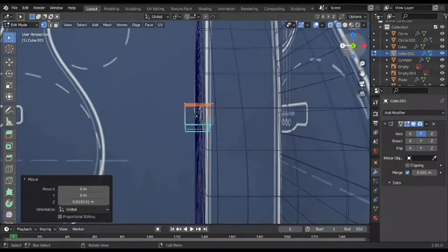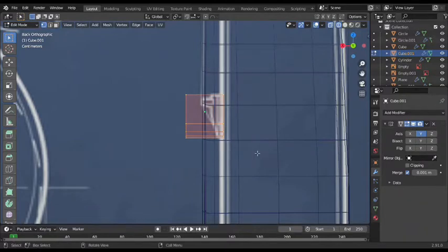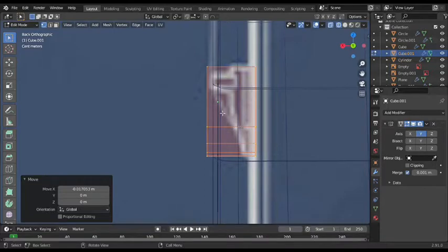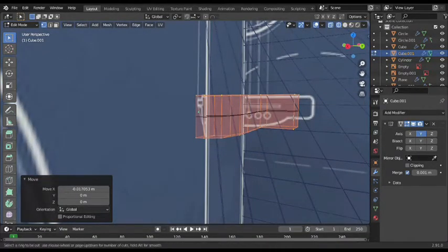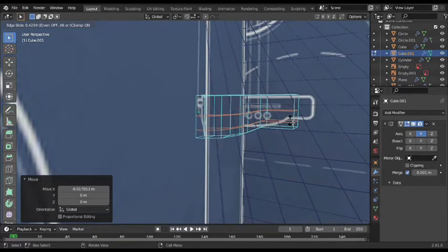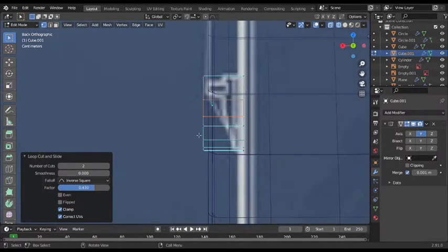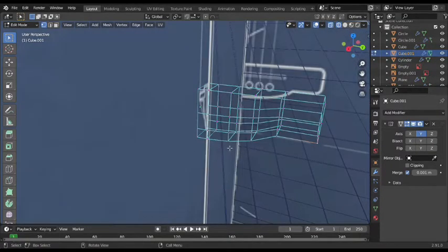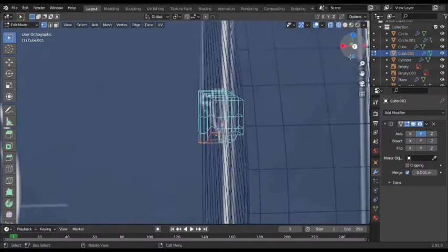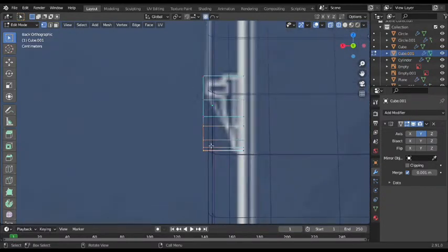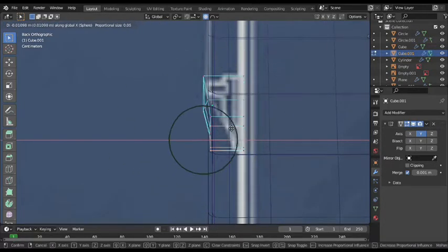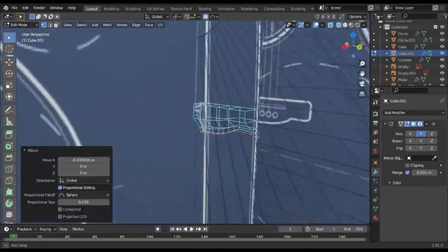Cool, this looks awesome. I'm gonna shrink this by height a bit now. So for that, scale X, I'll place it here. Now I want to add in some loop cuts, horizontal ones, up here, and okay. I'm gonna select this entire edge loop by clicking Alt. Then I'll bring them, enabling the proportional editing, G X. I'll scroll this down. Yeah, just like that. Okay. Seems pretty awesome.